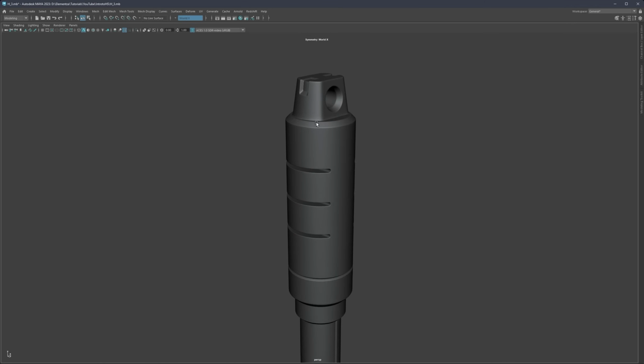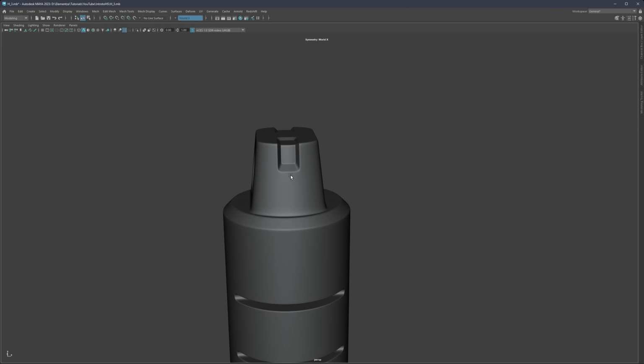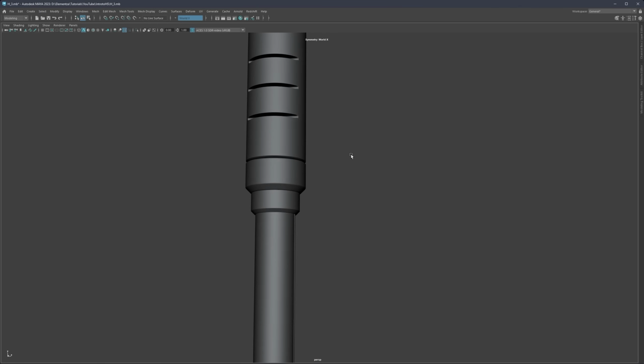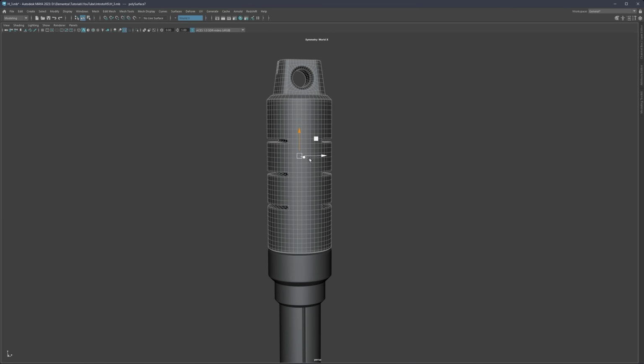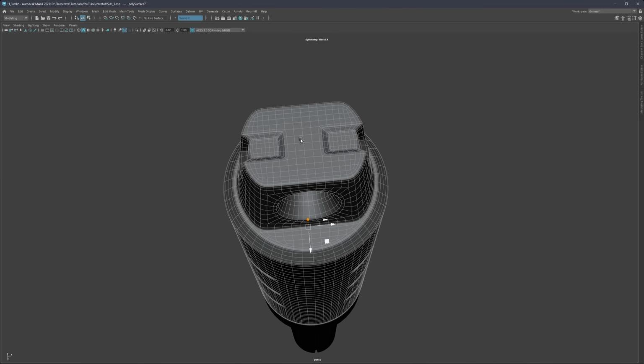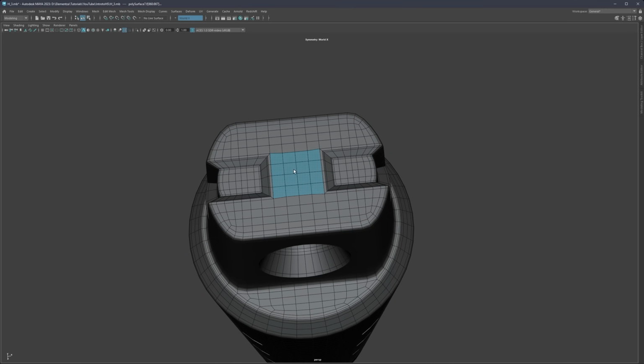more, let's say, room to play around and explore what else we can do here, and what kind of detailing we can add, just to make the shapes a bit more interesting. So let's see what we can do. Let's say here on the top, right in the middle, I would like to create a small circular opening. So let's do this a bit faster. I'm going to extrude, and let's do circular components, radial offset, and it's going to twist this in the middle.